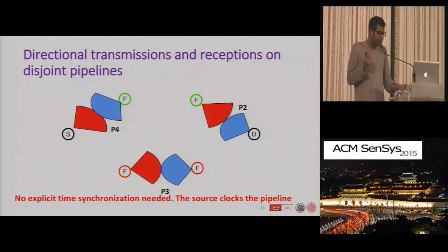And an important point of our protocol is that it doesn't need any explicit time synchronization mechanism. All the changes in the antenna direction are triggered by the transmissions that happen from the source node. So there is no need to have explicit time synchronization on the pipeline.